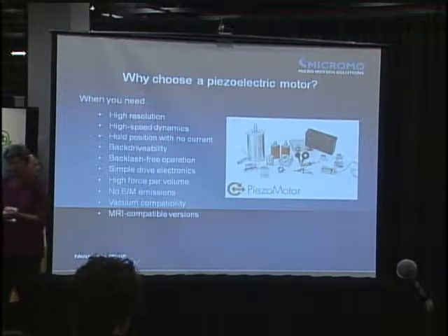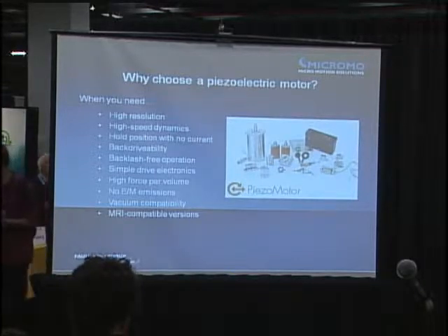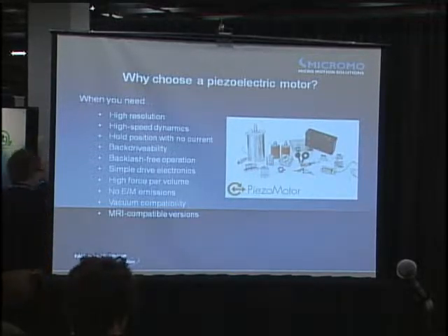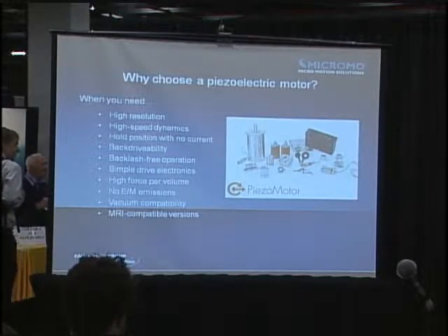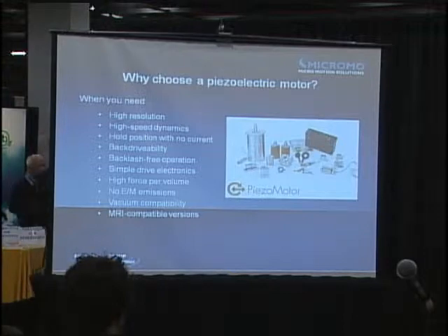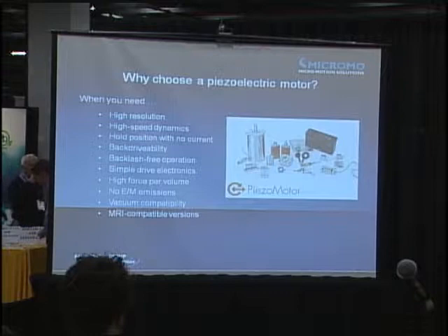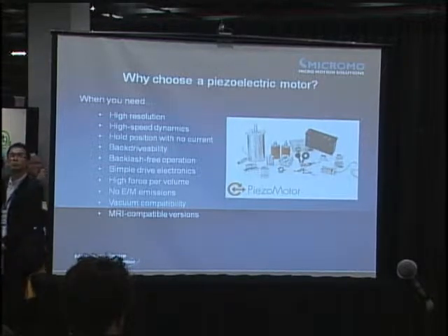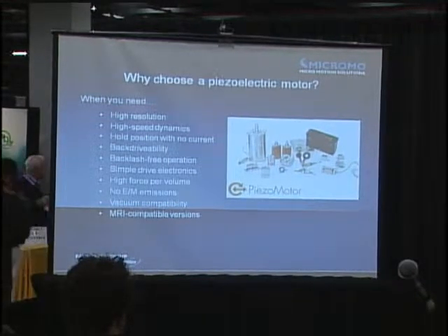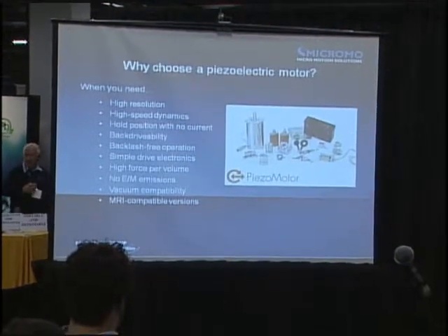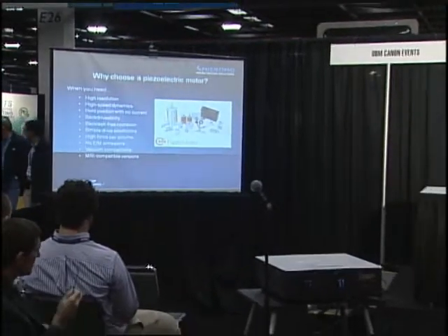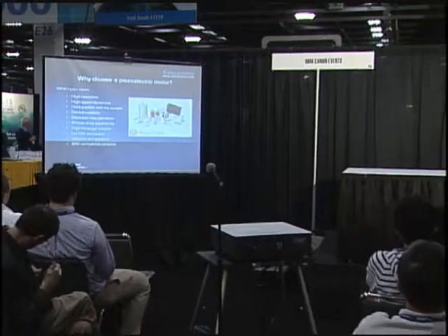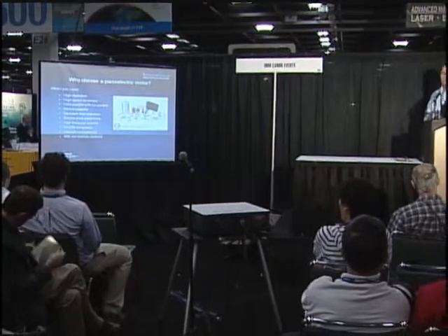They've used these in a lot of fiber optic applications as well. When you're positioning mirrors, fiber optic, when you're looking at wavelength splitting, nanometer positioning becomes very critical. It's a backlash-free device. There's other piezo motors that have extremely high acceleration, but the distance traveled is very short.